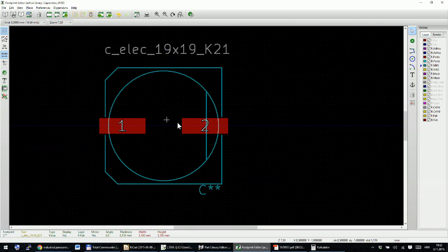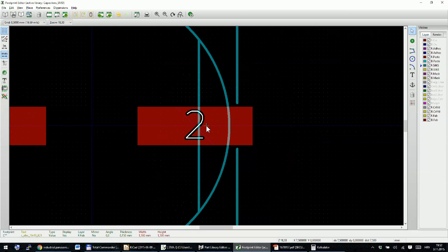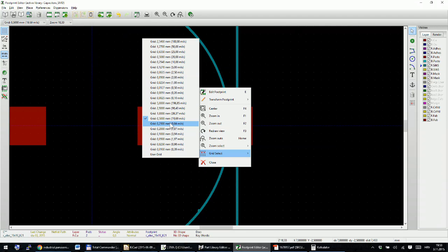And you are right to ask, because when you send this to your PCB manufacturer, silk screen, these blue parts will not go over copper exposed parts, and we can repair this part here to look better.